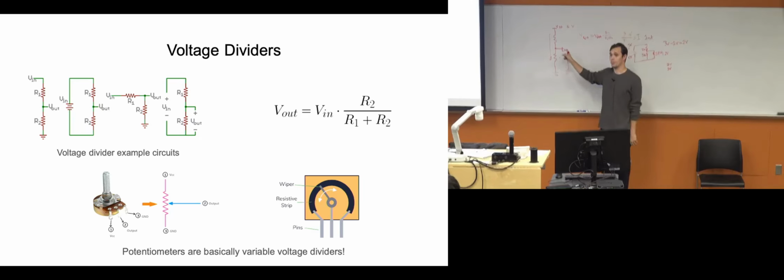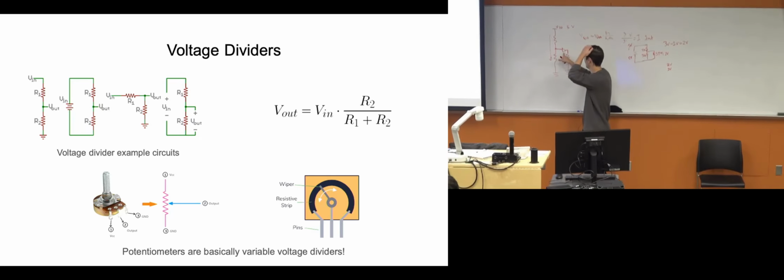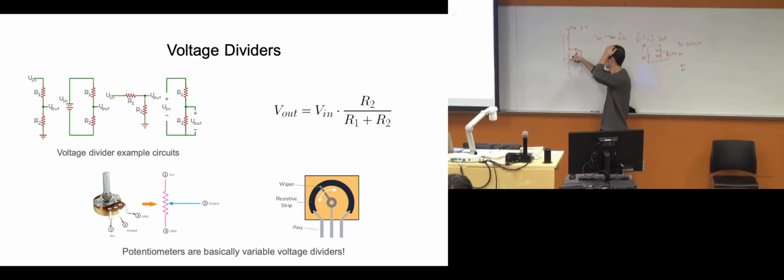This is also important, probably not on this exam, but we will definitely ask you something about this on the second exam. You'll learn about what output buffers are. Basically, they take in an input voltage, right? In this case, we had 3 volts here, and it isolates it from this side. So you can guarantee you put 3 volts here without letting this circuit affect here, right?